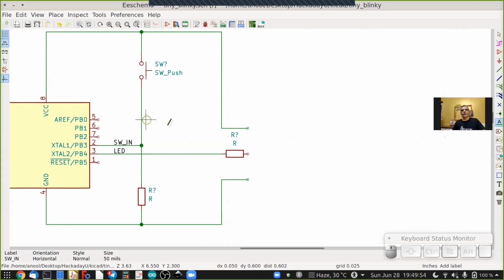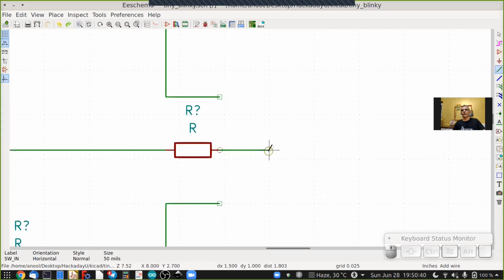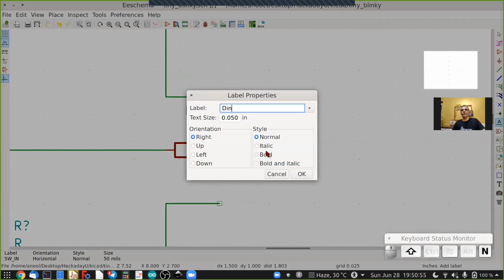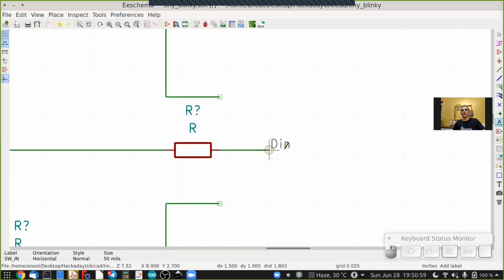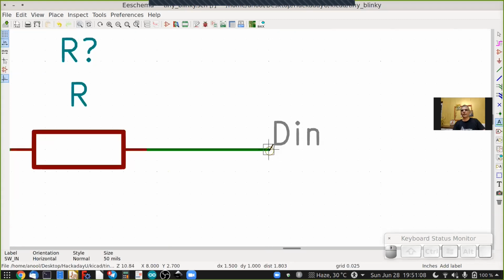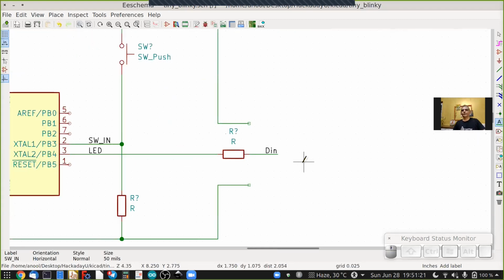There we go. And now let's add in the remaining net labels. Place the wire over here, end it over here by double clicking it like so. Then click on the net label icon, place it on this hollow green square over here, give it a name, be in, select OK, and I can still move it around, so I can rotate it, place it over there.